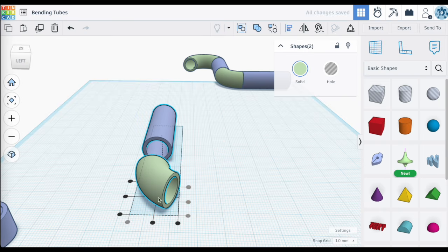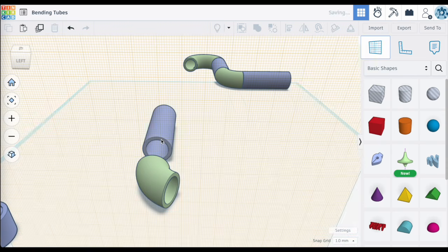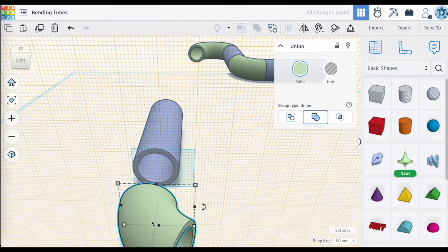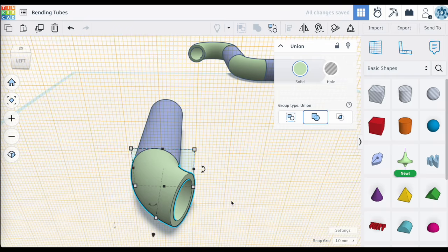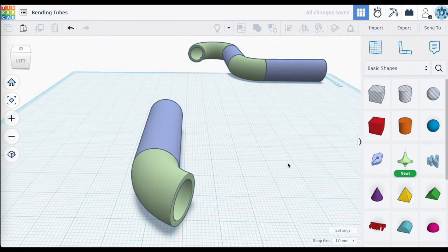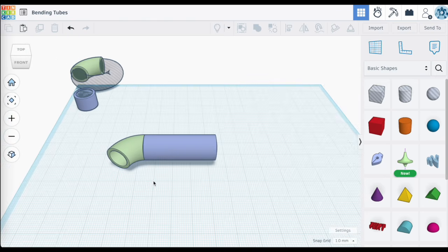So something like that. And then, as I said before, using something like the work plane tool, putting it on that flat surface there of that opening of the pipe, then selecting this, and just dropping it, or D, to that work plane. Select the work plane tool again, and just click somewhere else on our work plane, and that gets rid of it. Perfect. That was easy.